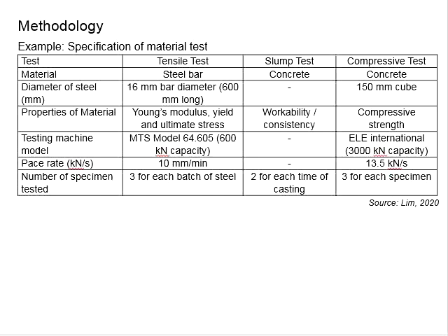You need the properties of the steel and concrete, especially the strength property, which in this case will be used to calculate the maximum capacity of the samples tested within the research program. Therefore, you will need to use the right numbers so that you can accurately predict the strength and capacity of the specimens. The compressive test was conducted in order to determine the compressive strength of the concrete used in the preparation of the test specimens for your research program.